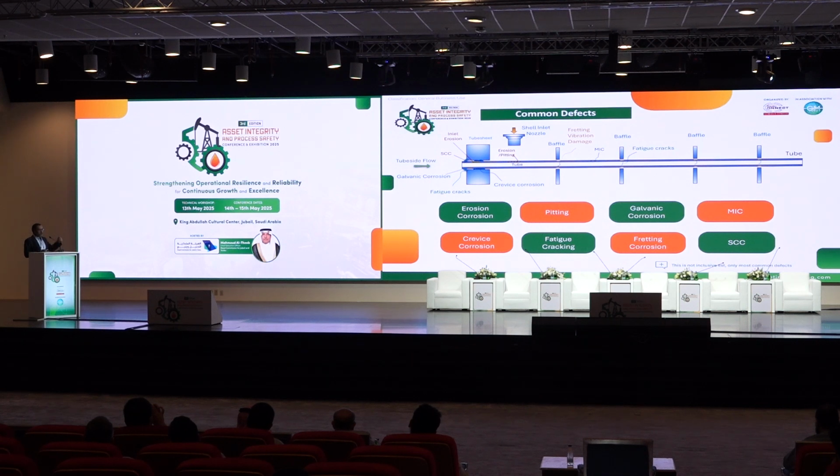Whether it is stress corrosion cracking, and we'll see in a separate slide the main factors and why we can think about it mainly in the tube-to-tube sheet joint, crevice corrosion and how to eliminate it, because it might be faced in the tube sheet to tube interface at the hole between them, and erosion corrosion, which is mainly at the inlet of the tube, if it is there by any means, galvanic corrosion based on the material selected, either between the tube and the tube sheet or between the tube bundle and the baffle itself.